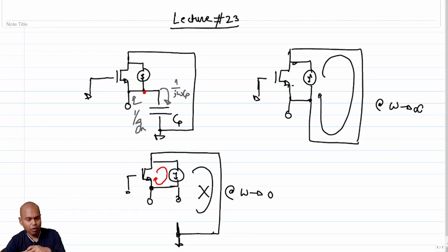Now the practical problem with biasing the cascode with high overdrive is that you will end up with headroom issues. So that is why in most design considerations you do not actually give the cascode a lot of overdrive, but you simulate and check for what particular overdrive, or how far below your omega t you need to be, because if you are already 100x below, you don't have a problem.